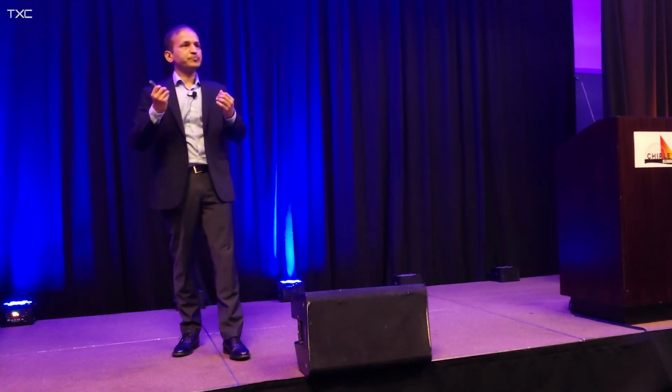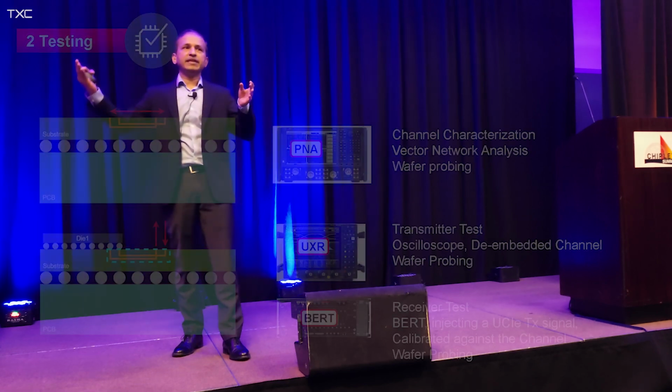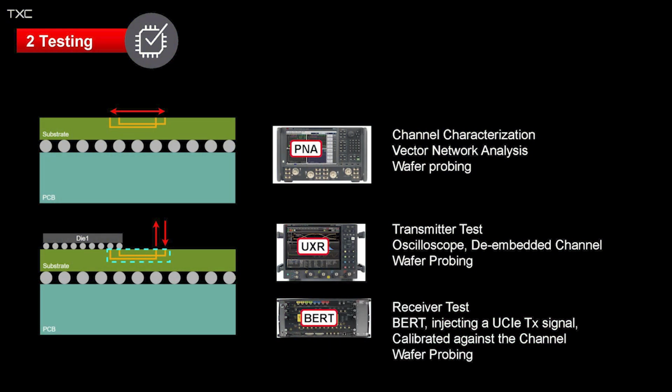So here are a couple of strategies on how you can do testing in the chiplet environment. So let's take a look at the passive structures. Everything after the signal exits out of the chiplet, all the passive structures, all your through-silicon vias, the packaging, the small bits of transmission lines, you could use microprobes and measure it using a network analyzer, out comes an S-parameter file, and you could use that for your testing.